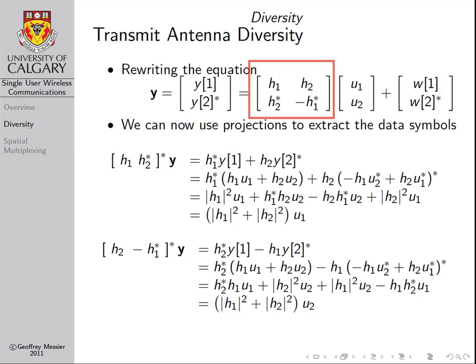As it turns out, there's also a technique called quasi-orthogonal space-time block coding, which gives you column vectors that are only partially orthogonal. So there's some interference between them. However, your data rate penalty is a lot less than with truly orthogonal space-time block codes. So there are many codes, and it's a very interesting area to examine all of the trade-offs that exist. But it was the original paper on Alamouti coding that was the start, or the genesis, for all of this subsequent interesting research.